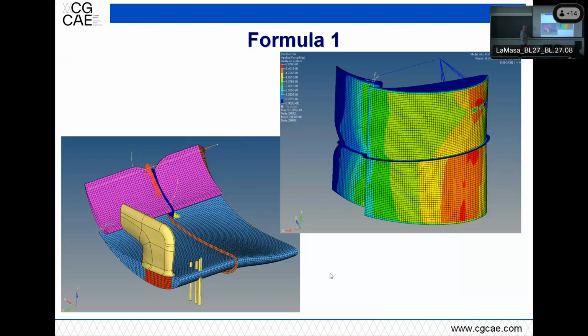You need to check also for local instabilities. And in theory, you should also take the deformed shape and pass it to the CFD department. They should remesh and recalculate the pressure distribution on the deformed shape, and give you back the new pressure distribution, and you should iterate this process until you stay below a limit that can be chosen.